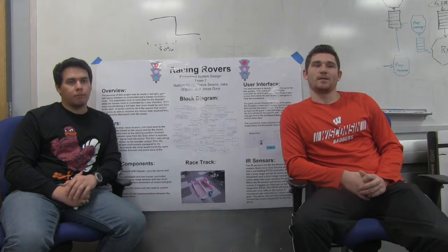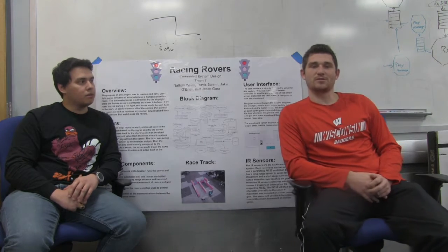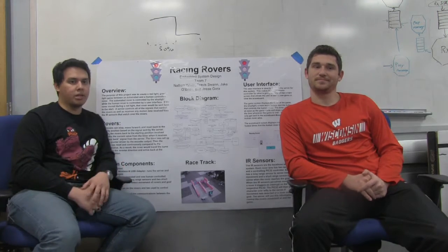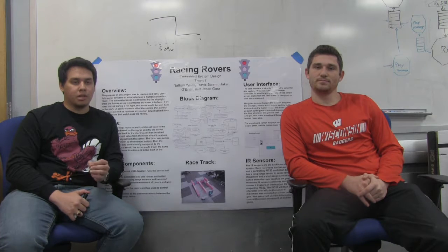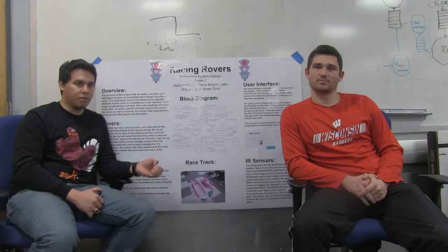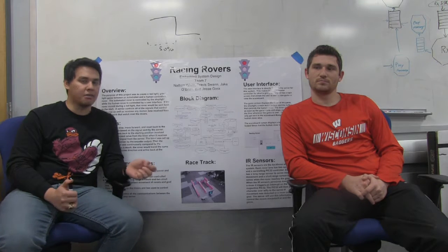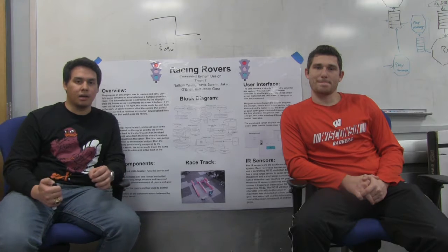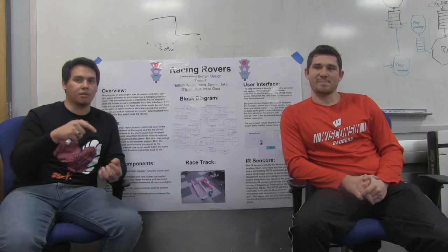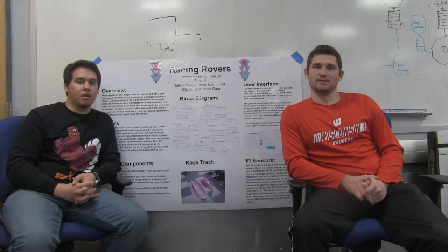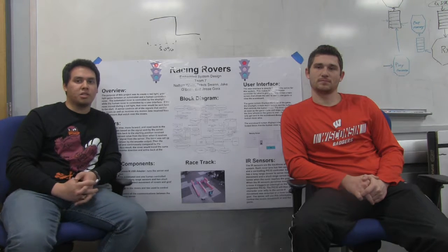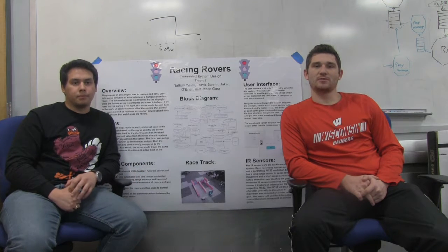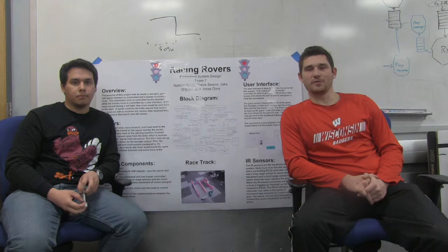The next thing we encountered was sort of a time delay. With the way the code was set up at that point in time, there was a delay between receiving the commands and actually executing the commands, which was about a 3-second delay, which was too long. So to fix that, we decided to change the actual changing of the PWM duty cycle to the interrupt handler, while still maintaining the state machine separate from that. After this, we deemed that the rovers were ready to be integrated with the other parts.